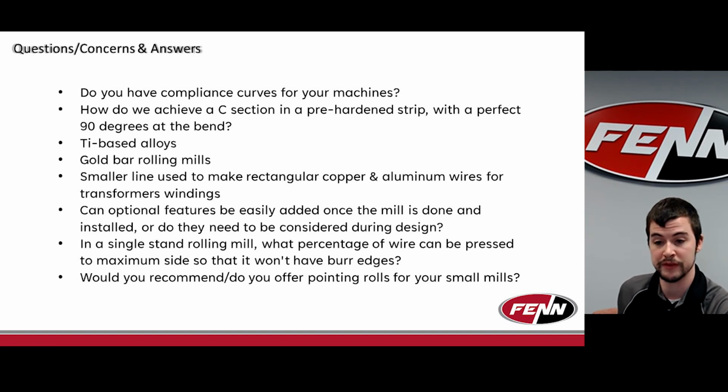We've run certain types of materials and, based on the diameter of the roll, determined how much we can take for our largest hits based on grip, as well as, based on starting thicknesses, what we're expecting to get for natural spread, which in strip isn't that much. For round material, you'll see it a lot more. So we have done roll curves and things of that nature as well. And in general, we have calculations that we can provide as a reference point, and then we can talk in more detail depending on different material properties and hot versus cold, about what we typically expect to see from a standpoint of roll grip as a minimum. Depending on the material tendencies and the roll surface, you can usually get a little bit more or a little bit less than that, but that can at least give you a good median range.